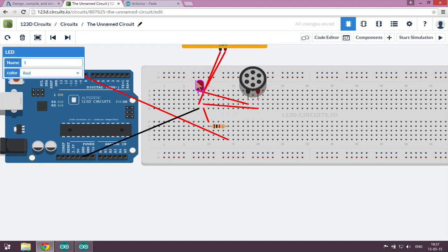Your layout can vary. I just want to make it work. Here we go. See? This is also a way to have a DC motor spin up and have a certain rotational speed. You can use pulse width modulation to pulse these motors to make them go faster or slower just with a digital output port.